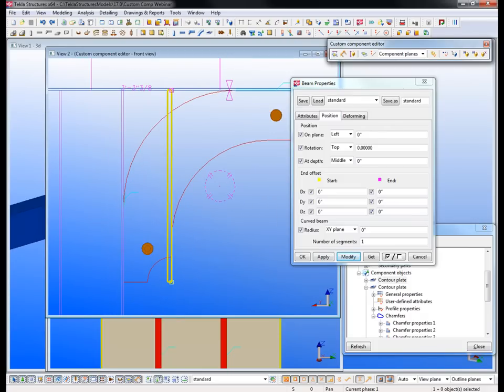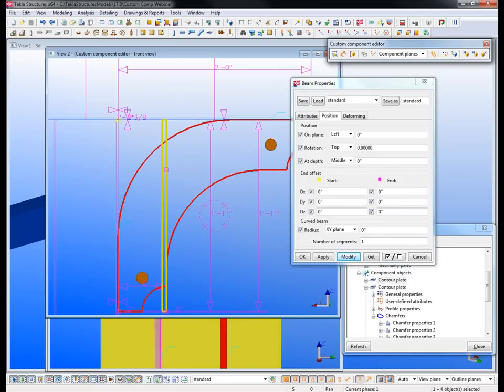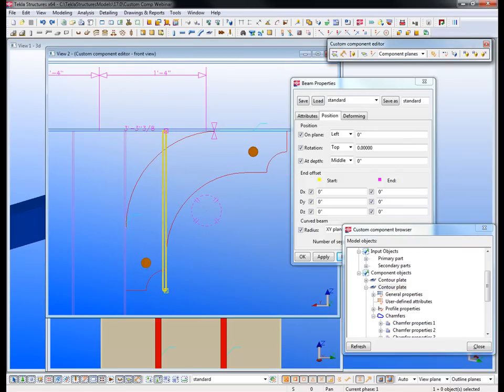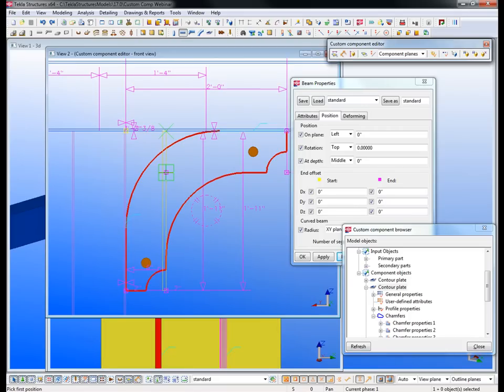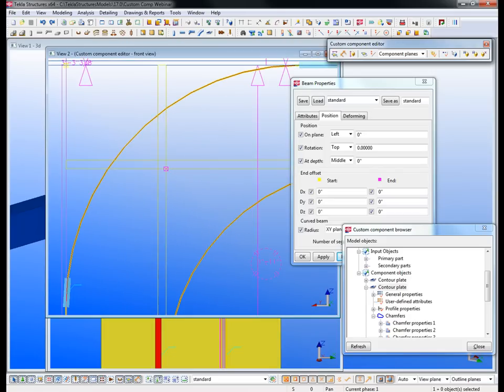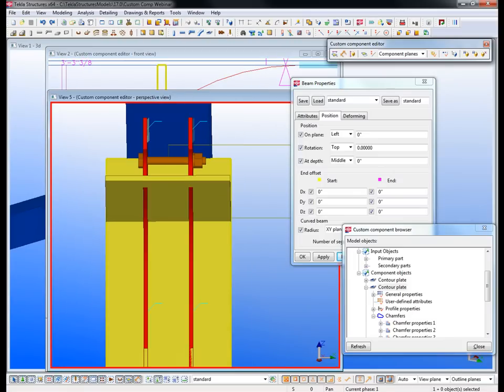So this is one technique you can use whereby you're almost creating a dummy member, which won't feature in any of the component, but it just gives you some extra assistance in creating a plane or something like that, just to make the actual creation of the component easier. Yeah. And I'm modeling this with matching the same handles, so that the distance here, this 1'11" binding, I'll be able to apply the same thing here and control them. But what I'm going to do is create with these plates an intersection right here of these points. So let me place that in. So now I can bind to these faces here to control these handles. So I'll go ahead and jump back